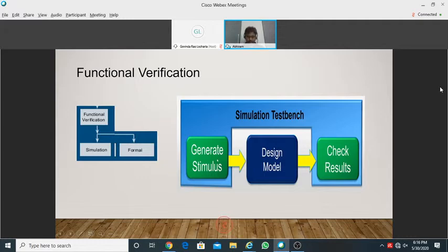So the left hand side stimulus part is where you generate, for example, if you say I'm going to support 100 Gbps, you need to have an Ethernet generator at the left hand side, and you pump into the design. Now you will see, am I really getting the throughput of 100 Gbps? That will be done at the right hand side. So in a simple description, is your design working as expected? That is how you test: you give the stimulus and you check the results.